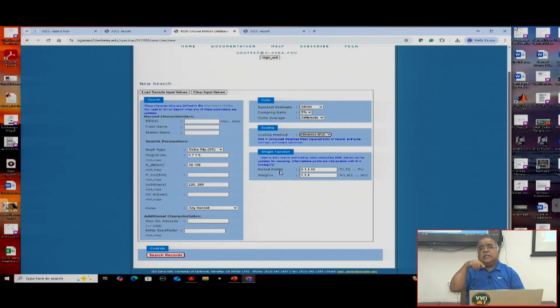There is a design spectra, and there might be the time history. So I have to multiply the time history by some amount, so that from this multiplied time history, the response spectra is calculated, and that response spectra should match with the design spectrum, right? So in that way, design spectrum was being scaled, right? Now it is not possible to match entire period, all the periods.